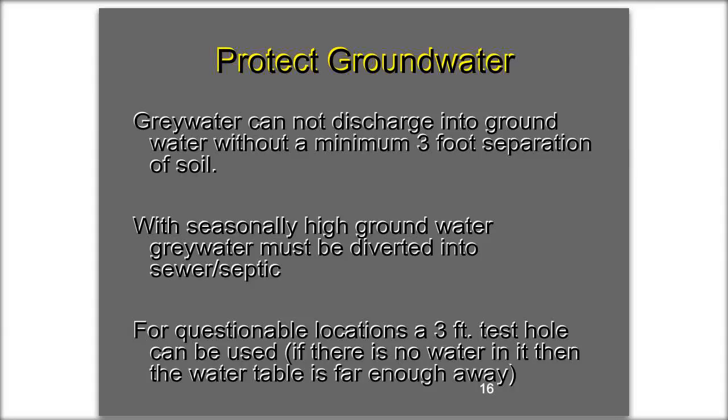But it's a really good requirement because you're having to prove that you're within a safe amount of distance. You're not having to actually prove where the groundwater table is, which some codes do have that requirement. And if your groundwater is 100 feet down, it's really hard to prove that. But if all you have to do is prove it's not 3 feet away, then that's not so hard. You just dig a hole.